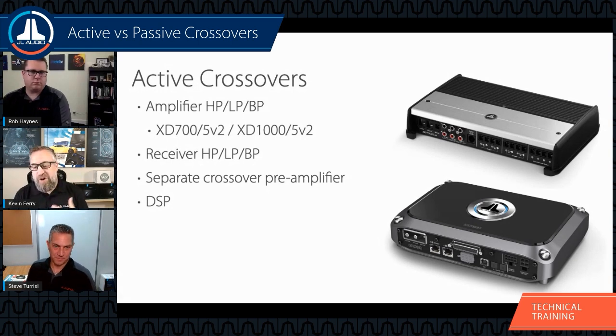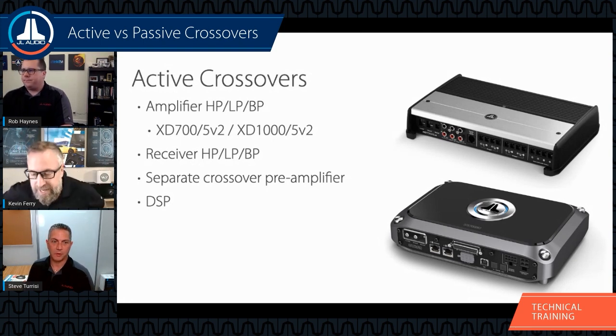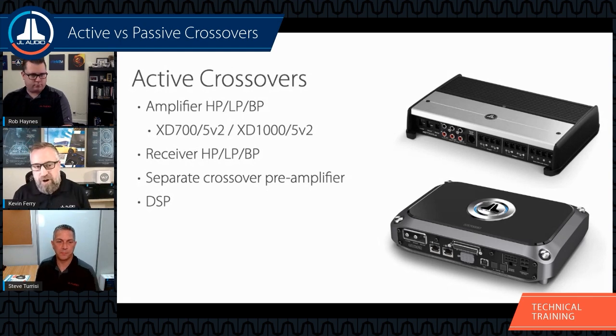And it gives us the most fine-tuned way to do it too. When you're looking at an amplifier, you're kind of turning a dial and looking at your frequency response. But with DSP, you're looking at the exact number that you're changing it to, and the slopes, and all of those other things that you can go in and change too. So it does give you a lot more options when you are going into DSP.